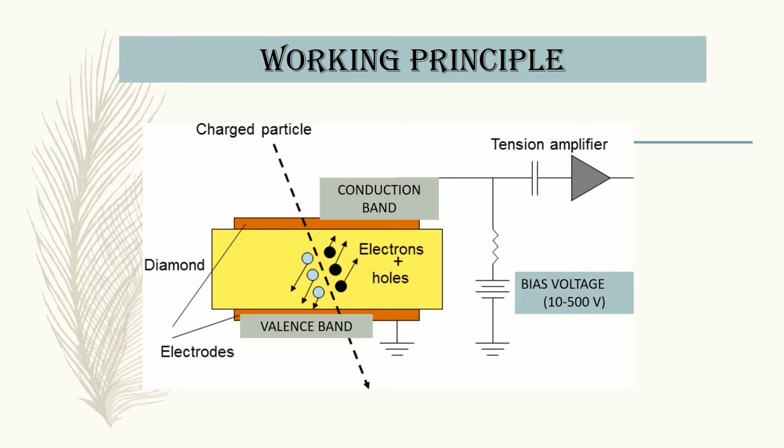Furthermore, the electrons at the traps create space charges, which give rise to an electric field opposite to the applied bias. This concept, called polarization, decreases the collection efficiency, rendering once again a nonlinearity of the detector.